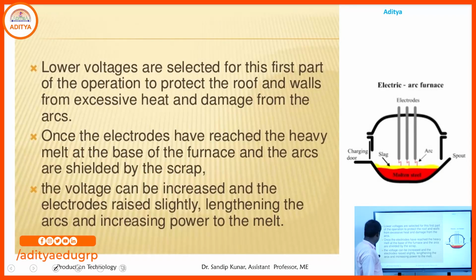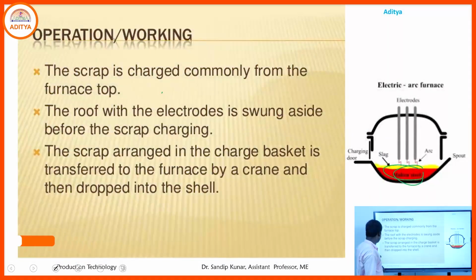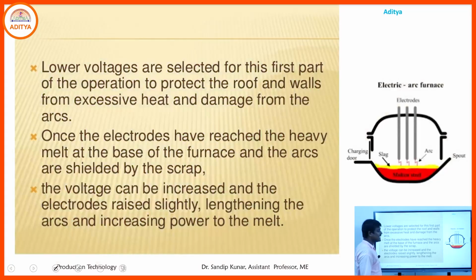In that case, first we apply the lower voltage. Due to the application of the lower voltage, we slowly heat the scraps. If we give extra voltage, extra heat will be generated. Excessive heat may damage the furnace or also damage the arcs.